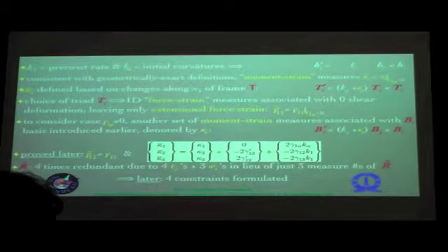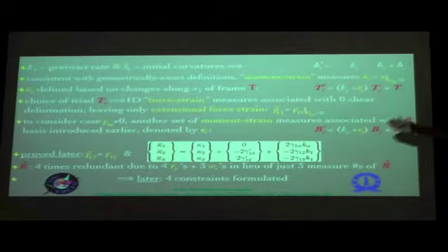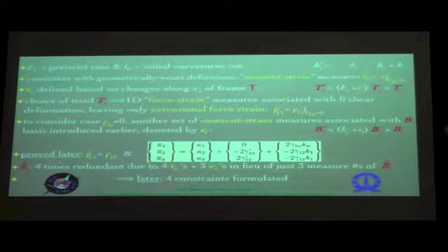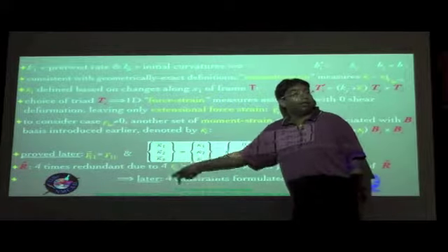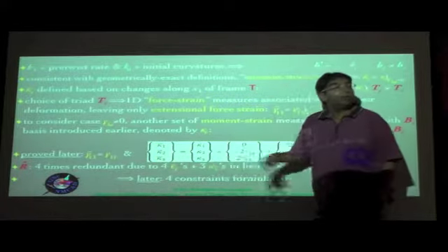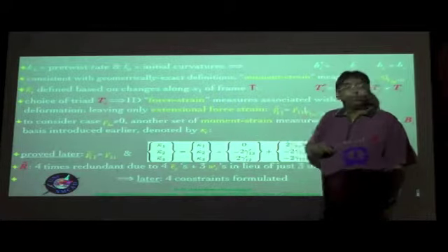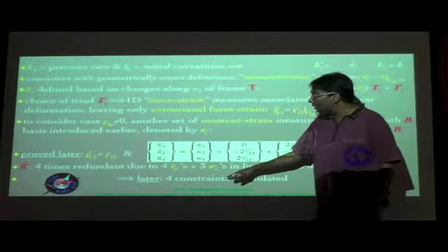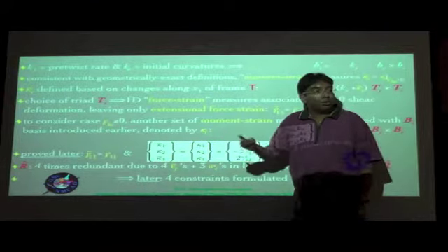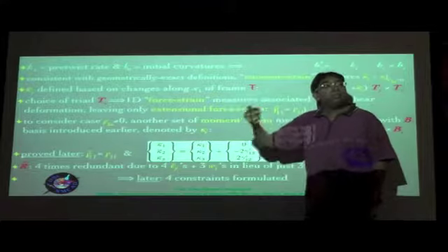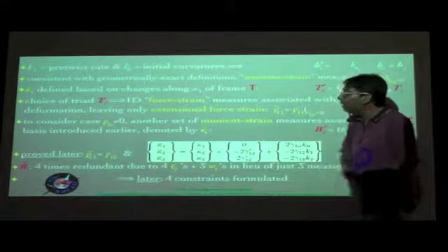Again, there is no unique way or sacrosanct way that these constraints have to be developed. Depending upon how you develop them, it gives certain meanings not only to the warping, because these constraints are on the warping, but it also gives certain meanings to the other quantity that you have, which is the set, which is now defining where an arbitrary material point goes. So once you define those constraints, it gives in particular a specific meaning to what these epsilon j bars are, and in turn to what the ui's and theta i's are.